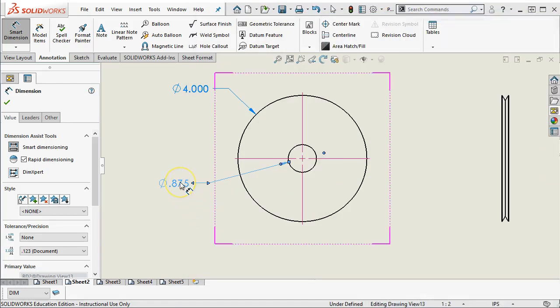So when I come up to the tolerance, I'm now thinking about this in terms of what it needs to do, what I have for tolerance. I would like the biggest that this can get to be probably 874.5, which would still be very loose, but more likely it's going to be 874.0 to about 873.0.